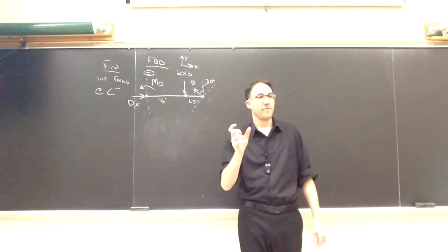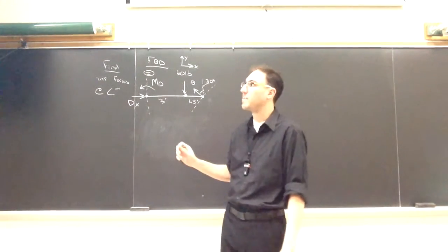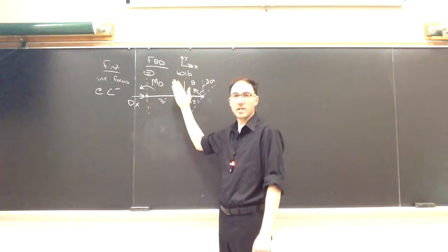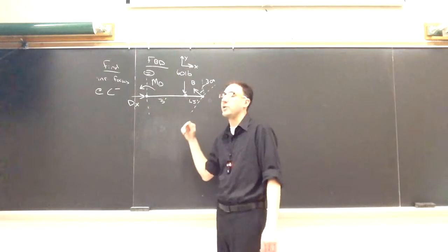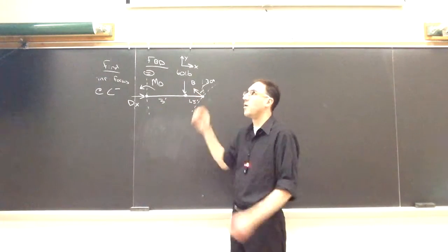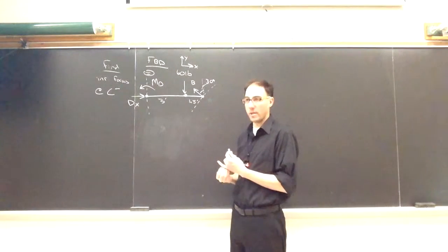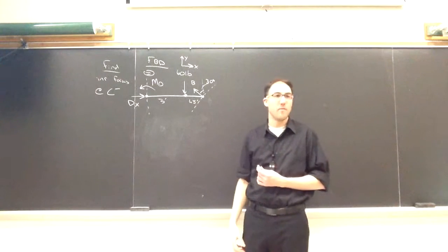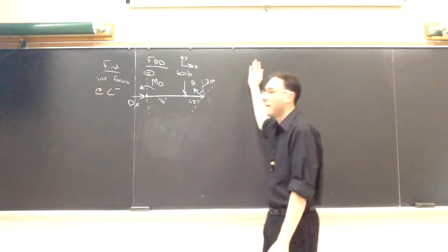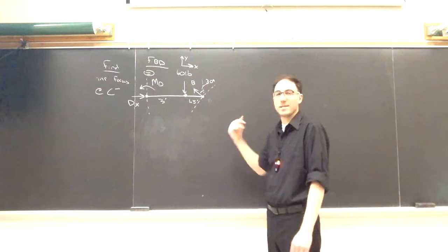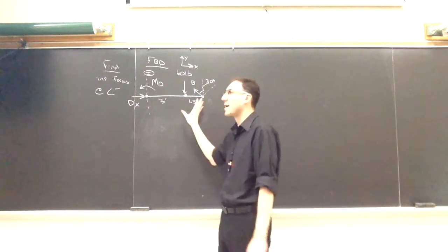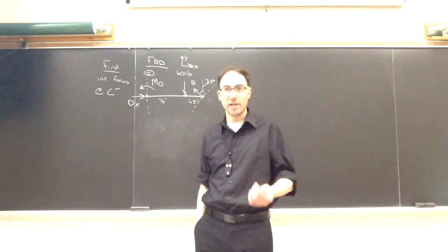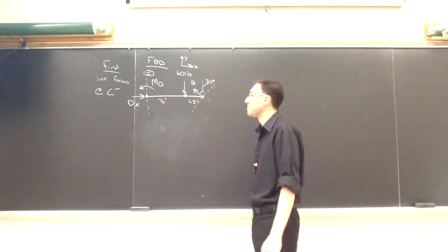So I'm not going to simplify it into a single point load. I'll simplify everything from D to C as one triangle and find its equivalent value and its equivalent location. And I'll treat CB as its own triangle, and I'll get a second point load there. So I will get two point loads, one for each triangle, instead of one. It'll make my equations just a little bit more to deal with, but it's not going to be that bad. So I'd recommend doing it that way. Just treat it as right triangles. They're just going to be easier to calculate their areas and so forth.